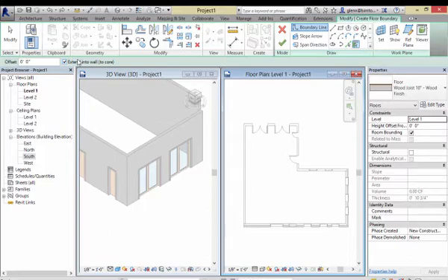And then with that core, when we're placing the floor, the question is, do I want the floor to come all the way out here, the outside surface, where you can actually see the edge of the floor from the outside? Or would I actually like it to stop back here at the face of the core? And we'll learn when we build things, that's actually typically the better relationship, to have it stop at the core and then let the finish wrap around the floors. That way you don't see the floors hanging out in a multi-story building. The finish just wraps over the whole thing. Okay, and that's what this choice is all about, extending the core.